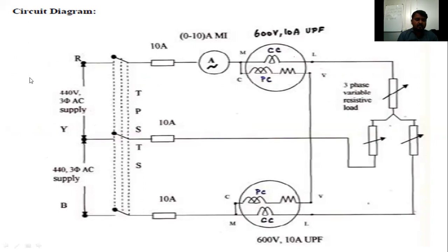Suppose a pole mounted transformer, that one came to your houses or our laboratory. By providing one socket here, the MCB, 3 lines came here. 3 MCBs we are going to use here. The three-phase supply came here. For each phase, this is R, this is B and Y. Like that, 3 phase supply came here. Once it came, I will provide the switch here.